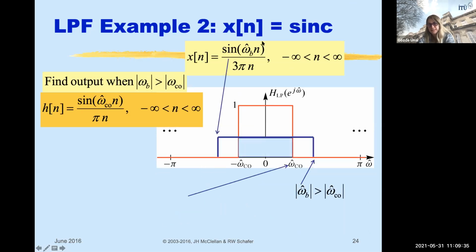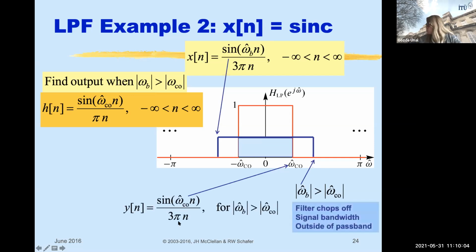Now, this is another example. When the bandwidth of the input signal this time was larger than the filter cutoff. Okay, what would happen? Now, it's not the same output, but those parts outside the filter would be suppressed to 0, right? Because it's a multiplication. So wherever it's overlapping here, that would be the resulting signal. So our result would be really now the filter itself.